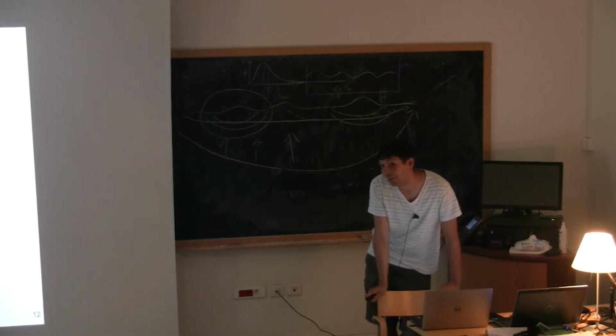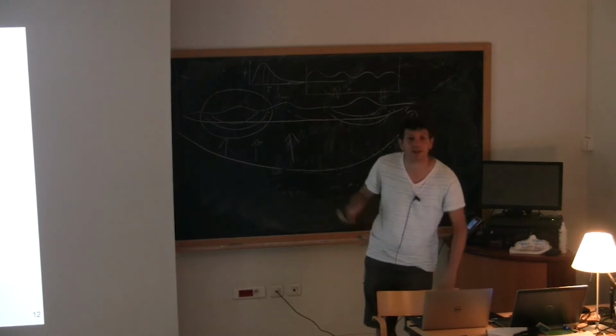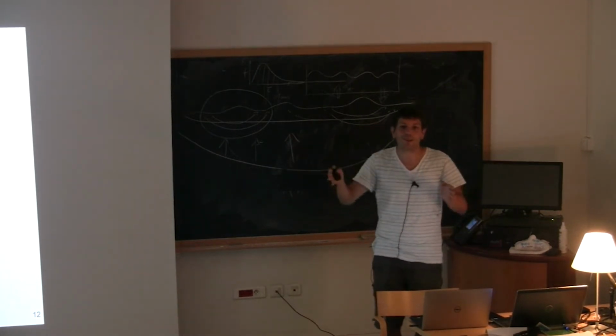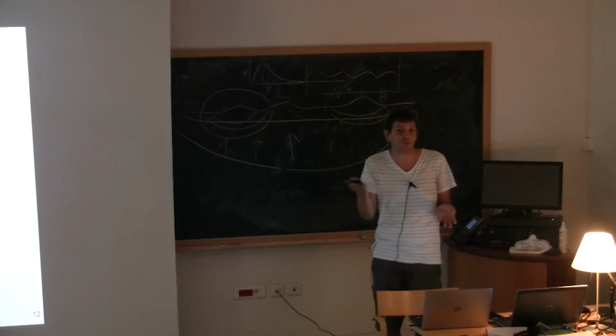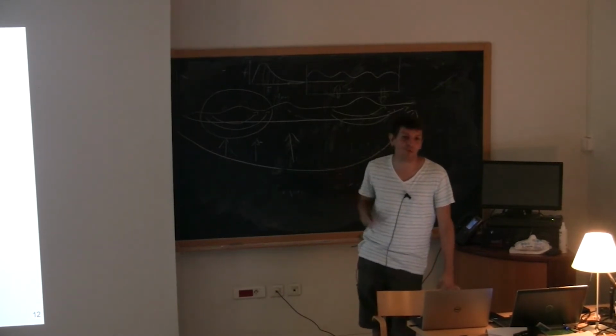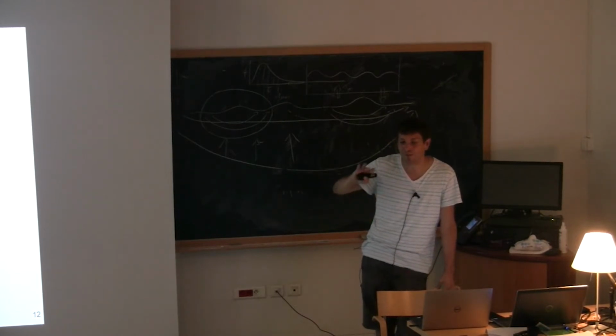So this is a very important question, and at Darcy scale you don't have boundary condition. I mean, except at the edge of your domain, but because you have an aggregate of fluid and solid, you don't have the boundary condition. But the boundary conditions are included in the Darcy formulation. So basically, in the permeability.